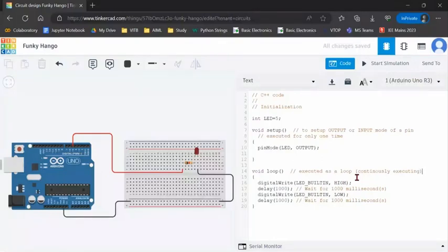Okay, so all the sections that we will be putting inside this will be continuously executing. And here in the loop, this is how it should be working. We will be providing the D5 terminal with a high voltage, like 1, and then after some time we will be providing it the 0. So 1 and 0 we will keep on making. Once we make it 0 and 1, it will keep on activating the LED, 1 0 1 0, likewise it will be showing.